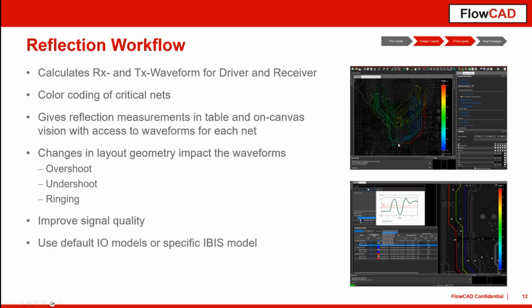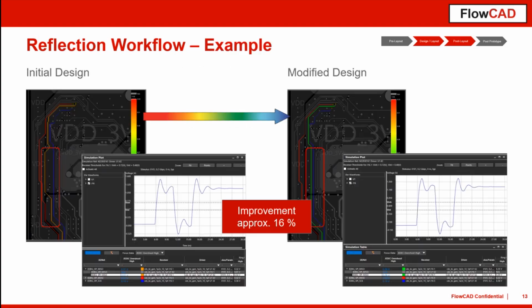As a result, you can now see the waveform that is created from the driver to the receiver side. In this case, we can also see that once we move the trace away from this gap over a solid ground plane, the ringing has been reduced, more or less significantly.